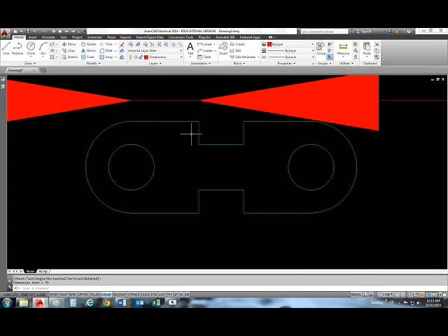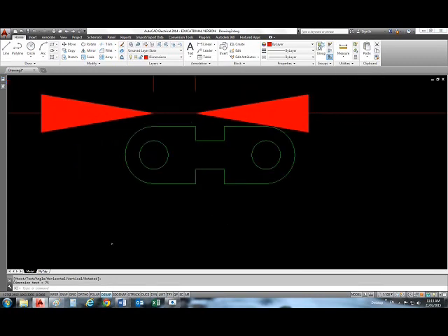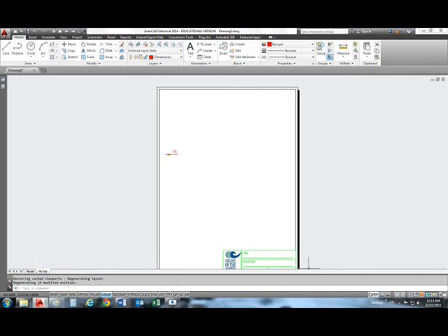And what happened here? Too big. Why? Same mistake as I've always been pointing out. Do not enter any annotation until you set your annotation scale. Don't set your annotation scale until you set your print scale. So let's go model space. Make sure it's unlocked. Double click the wheel. Let's get rid of this for now. Delete. Double click the wheel again. There it is centered. If you see it broken like this, just type regen for regenerate, and it looks nicer.